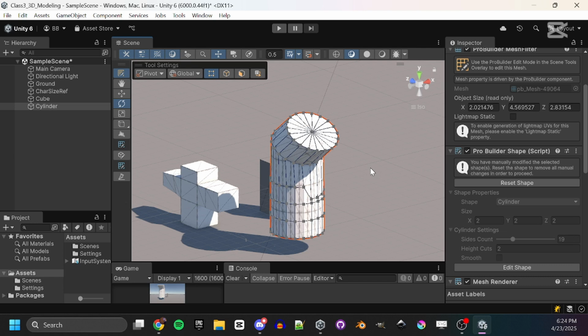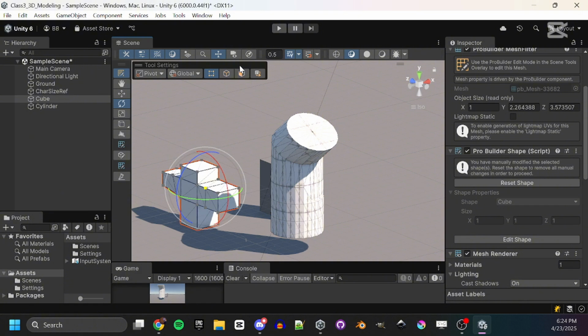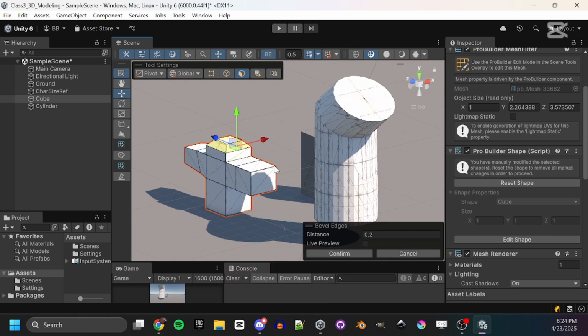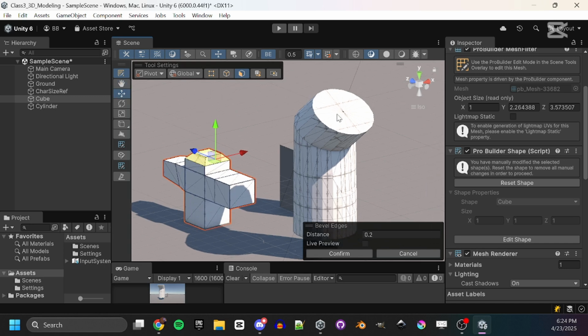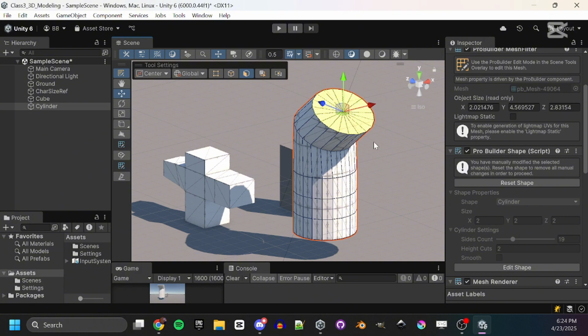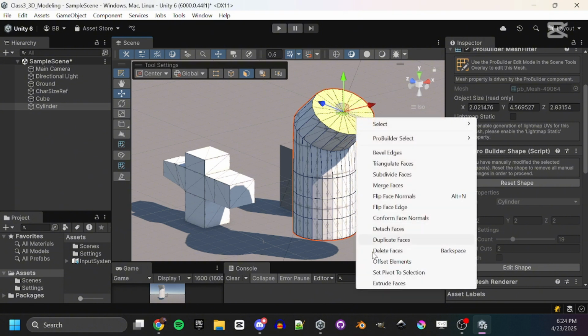How does Blender extrude? For example, one of the other things you can do is select a face, then right click and bevel edge. You see it creates a pattern like this, kind of chopping that up. And I could do the same if I get back to where I was, so I could bevel this as well.